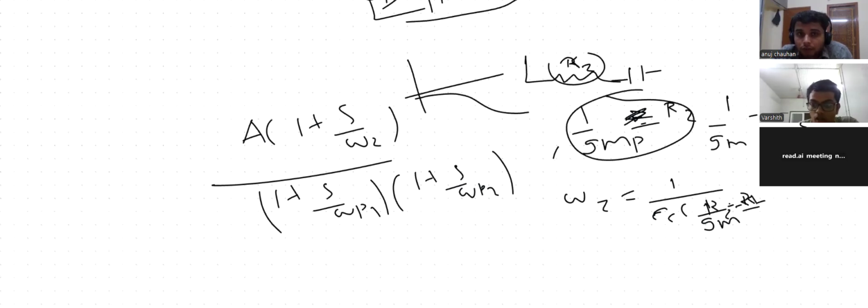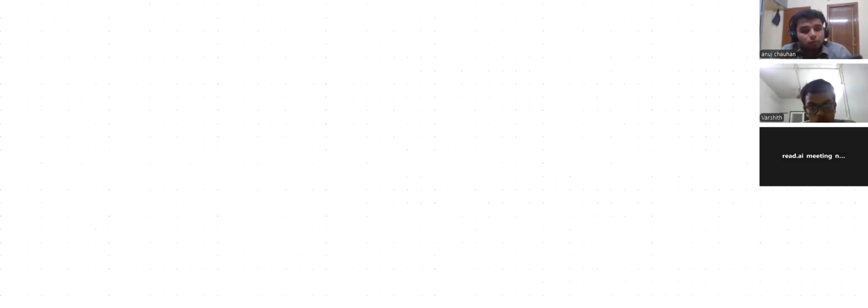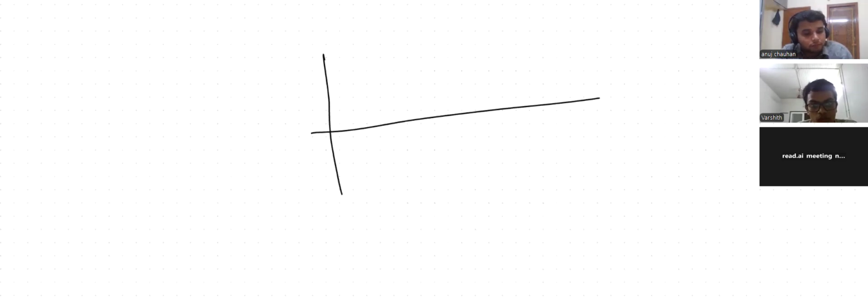Okay. Now it's correct. So you cannot take RZ lesser than 1 upon gm2, otherwise it would be in positive sign. Yes, yes. So this is the case. So what is the Bode plot now? Actually, it would be having some gains: gm1, gm2, ro2 parallel ro4, R1, R2.